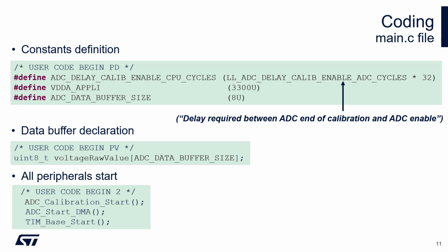We will need also to define the voltage of our internal reference. On our board, the VREF pin is connected to the VDDA, which is also connected to our power supply. We will need also to define the size of our buffer. After that, we will declare our buffer on which we will store the converted value.